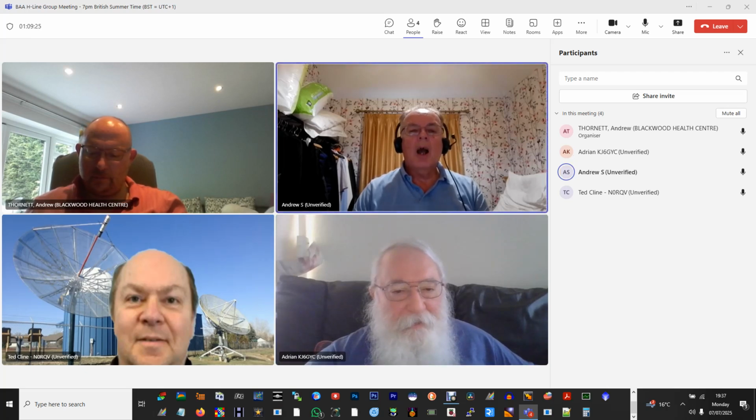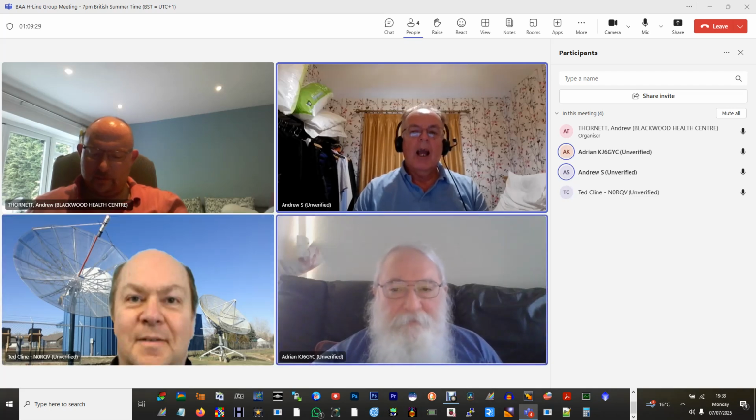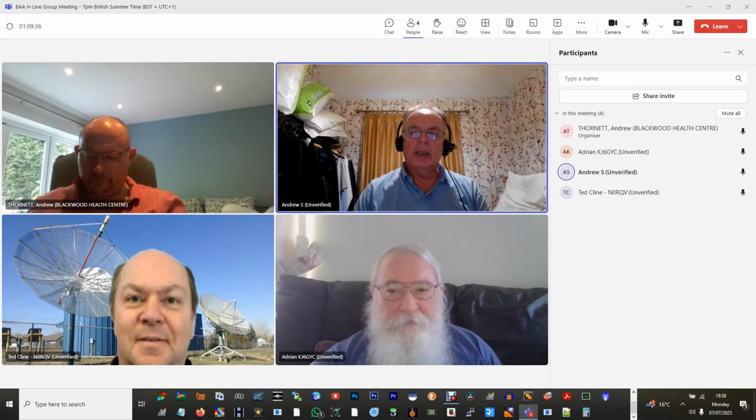Yeah, I've purchased a Nuand bladeRF, which obviously has broader bandwidth, but I've been having problems using it on the dish. I'm just not getting signals out of it, so I'm not sure why. I've been playing around with different receiver chains and amplifier chains, just trying to figure out what's going on. But at the moment, I've put the blade aside and I'm back on the Airspy on the dish.